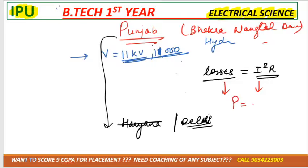So we have the formula P is equal to V multiplied by I. Here power is constant. If we want to decrease the current, then must the voltage be increased or decreased? If we want to decrease the current, then voltage must be increased.